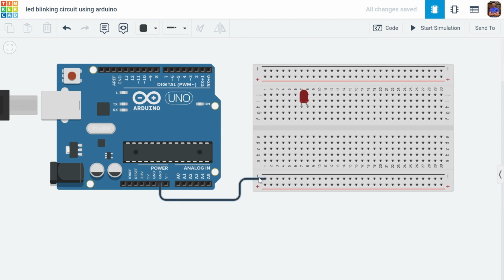This positive and negative, both the rows are not interconnected with each other, but each and every point over here is connected with each other internally. Similarly, if we look over here, these points are arranged vertically and they are connected internally with each other. There is a dividing over here and another set of internal connections in between the points.